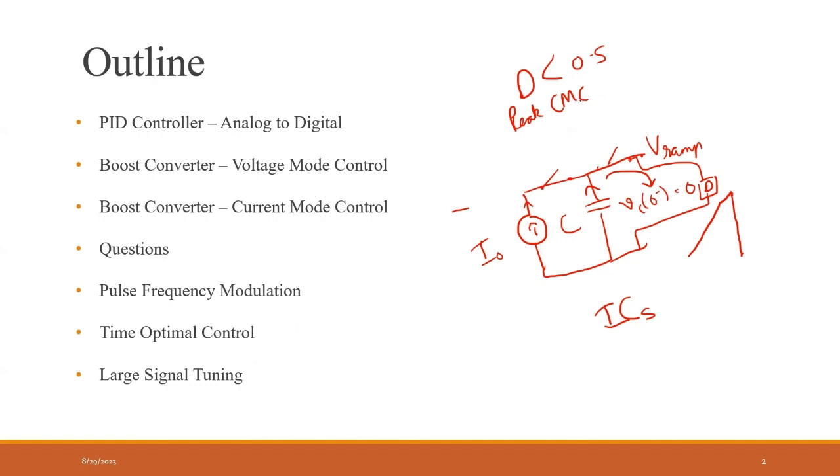No. For peak current mode control, if the duty ratio is greater than 0.5, then it is unstable. But should the duty cycle be approaching 0.5, or going away from 0.5? When will that subharmonic instability happen?